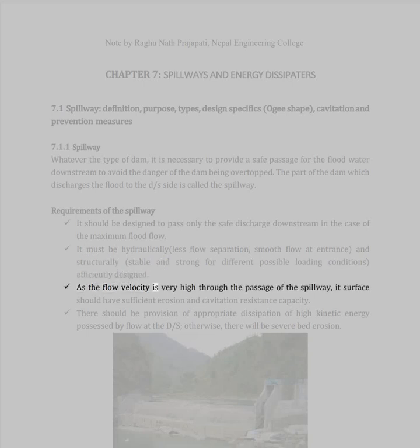As the flow velocity is very high through the passage of the spillway, its surface should have sufficient erosion and cavitation resistance capacity. There should be provision of appropriate dissipation of high kinetic energy possessed by flow at the D/S, otherwise there will be severe bed erosion.